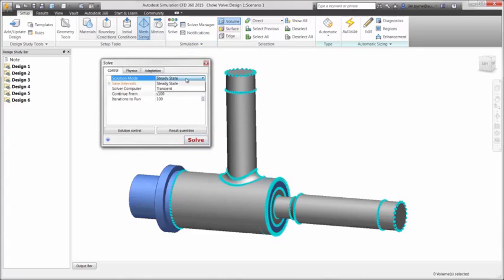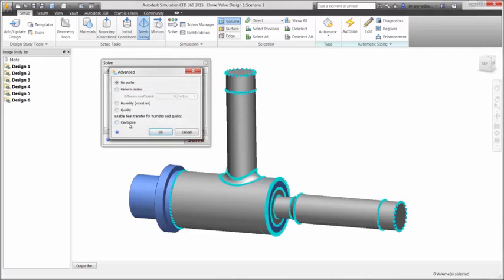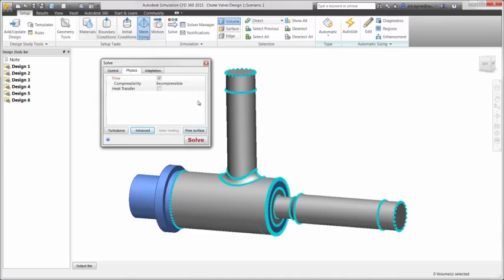There are several options available for calculation, such as steady state for the final flow result, or transient to view the change in flow or heat transfer over a period of time. Thermal solutions include options for natural or forced convection, conduction in the solid, as well as solar heating and radiation effects. For our purposes, we can leave these options unchecked. Cavitation can also be used to provide more accurate results in cases where the fluid reaches vapor pressure. This improves the accuracy of forces computed on the walls of the valve body.